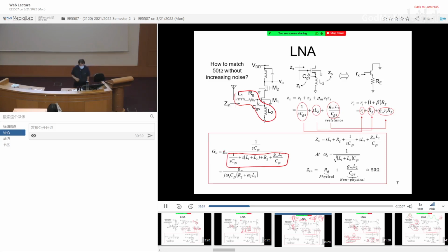And across all these things, only this component contributes to VGS, the gate to source voltage. So you put it at the numerator. Why is this important? Because only this portion, VGS, gives rise to the current. All the other components don't give rise to current, because the dependent current source is what? gm VGS. Only the VGS voltage gives rise to the dependent current source. So we use an impedance divider to figure out how much current actually gets generated.